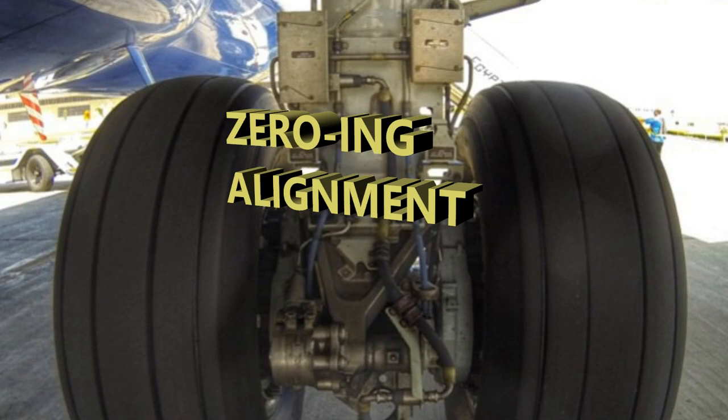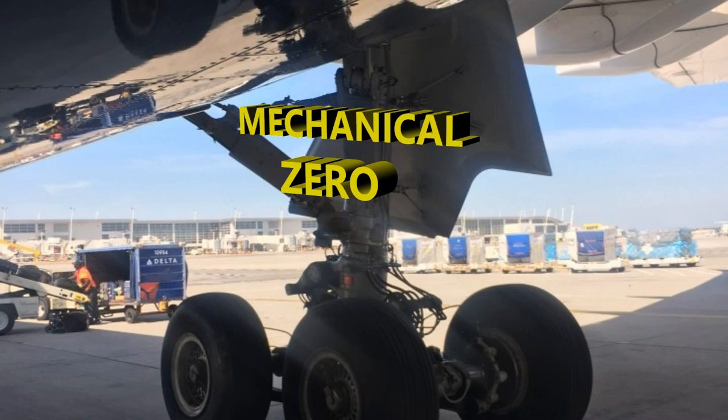And of course, before you do an electrical zero adjustment or alignment, you want to make sure that you do a mechanical zero. So that's why I mentioned them both together. You have to do a mechanical zero, making sure that the nose landing gear is physically aligned and centered within a certain range before you do your electrical zero of the rotary variable differential transducers. So just keep in mind, just follow the marks that are on the nose landing gear when it comes to zero positioning.